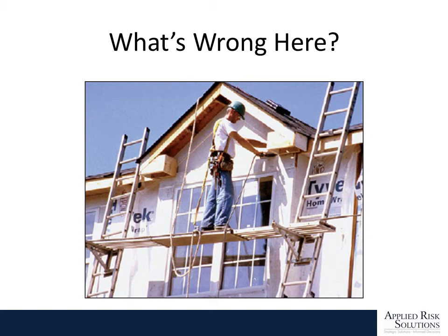And even if it did, that extra 3 or 4 feet he would be falling would apply tremendous forces to him, probably injure him. And that extra force would also possibly just rip whatever it's anchored to off the anchor point. The farther you fall, the more force that's going to be applied to not only the person but the anchor point. So it's very important, if you're using personal fall arrest, that you keep yourself at a point where you're not going to fall more than the 6 feet before your lanyard deploys to slow you down and prevent you from hitting the ground.